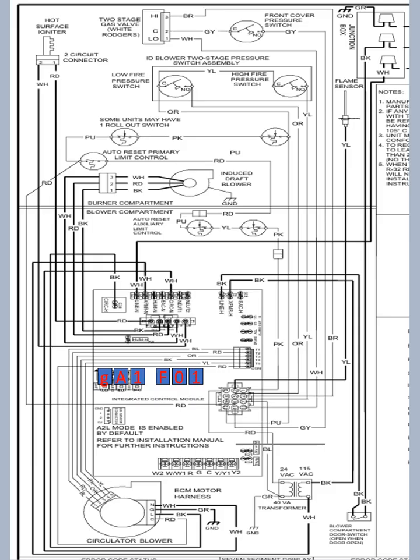The control verifies the auxiliary switches and the primary limit switch are closed by sending out 24 volts on pin 1, a pink wire, of the 12-pin connector through the auxiliary limits on to the primary limit and back down on the red wire to pin 8 of the 12-pin connector, as we see here in the diagram.